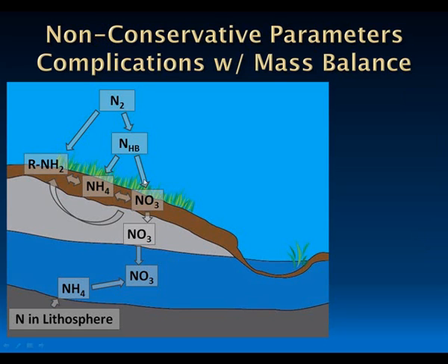So the last thing I want to touch on here is just the fact that because nitrogen and phosphorus are taken up by plants and can change phase between these various species of nitrogen, they are non-conservative. Sediment, I said, was conservative, obeying conservation of mass moving downstream. Salts in general are largely conservative as well.